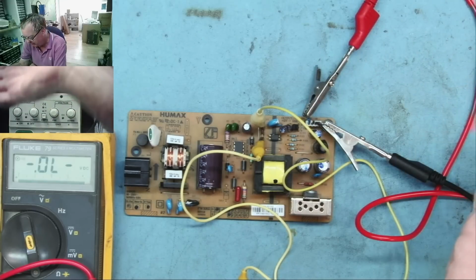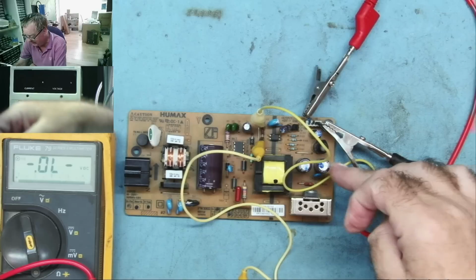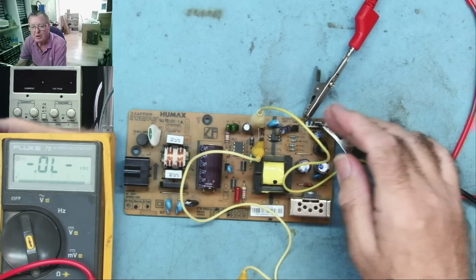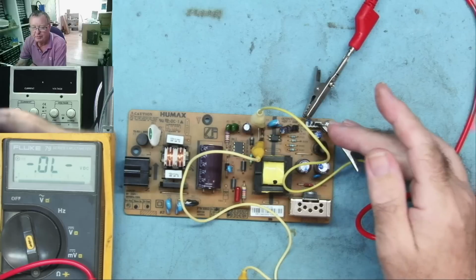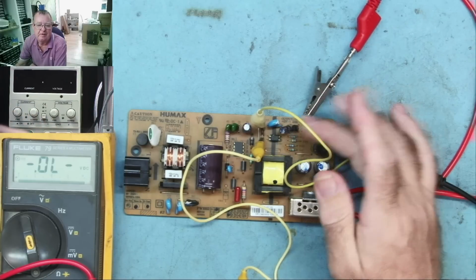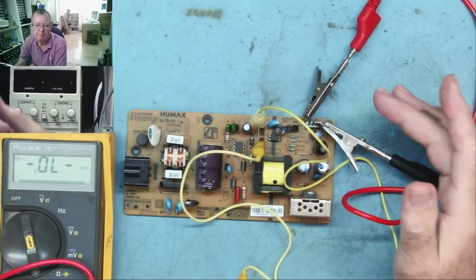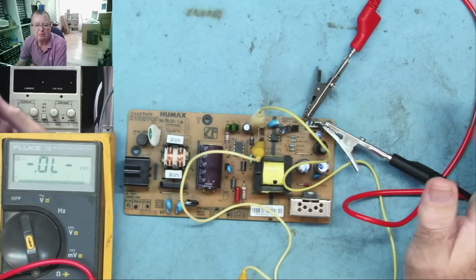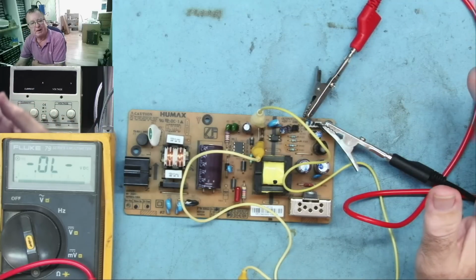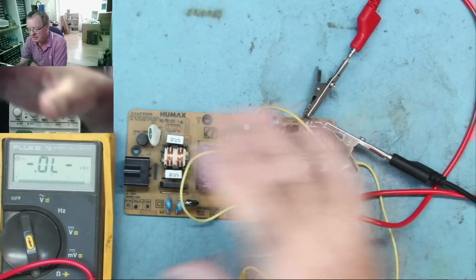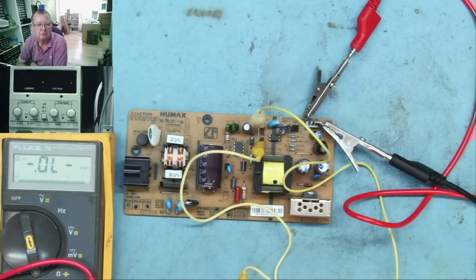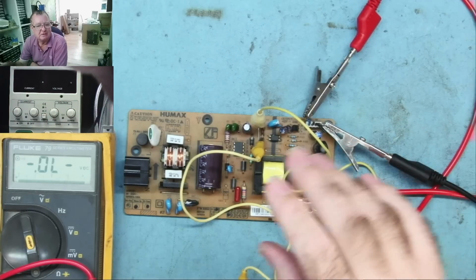Well, the answer is no, as long as you don't go above the rated voltage of the output capacitors, or if you had the load attached, you don't go above the rated voltage of the power supply. Now, to test the feedback circuit, we want to go a bit above the rated output voltage. So disconnect whatever load is normally connected from the power supply. If this is embedded in some device, maybe you can unplug a plug or just cut a track or something, but you need to be disconnected from the load.